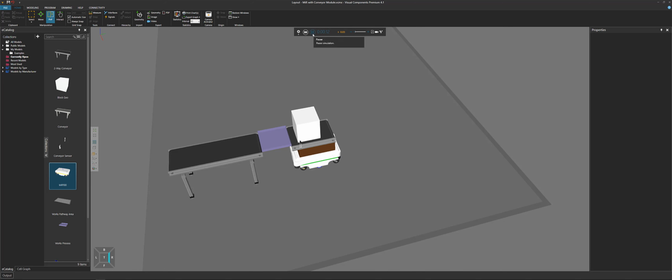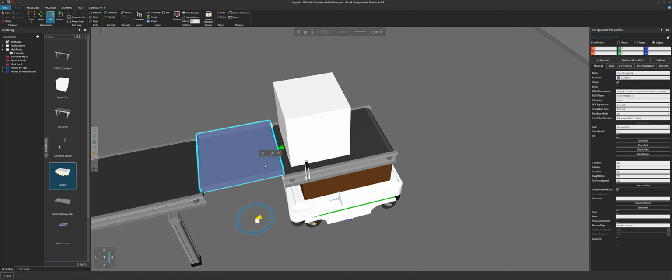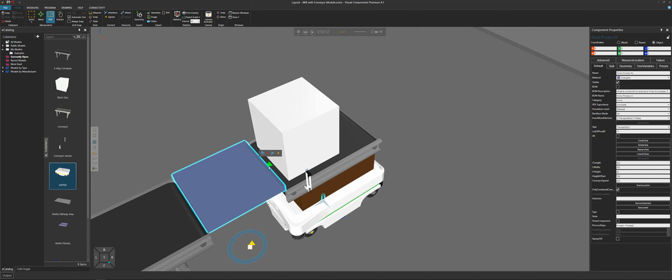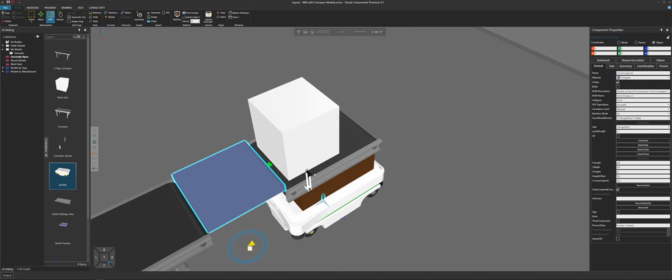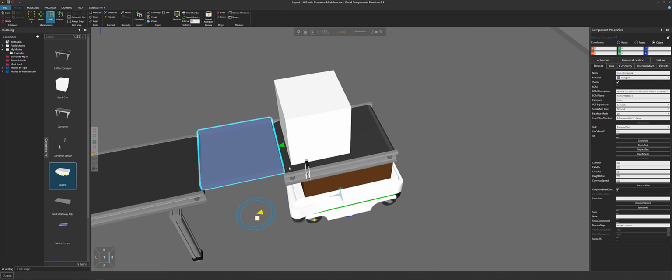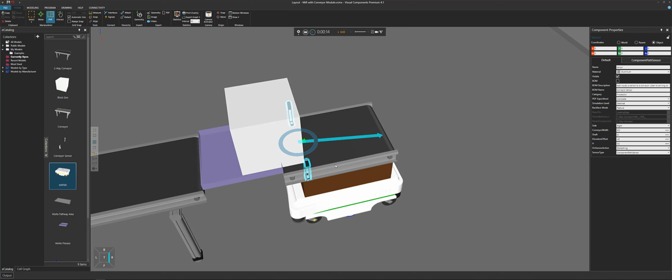And once we get here, first thing we have to do is establish a connection between this robot and this station here, so you can see it's connected. You may have seen yellow arrows here, but this is referring to its two-way path, so this interface here is definitely connected to our conveyor module. The paths are turned on, so that's why the part can move from this conveyor onto this conveyor. And both the station and the robot are told not to move or do anything extra because we're waiting for that feedback from our sensor.